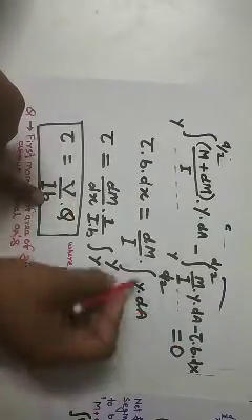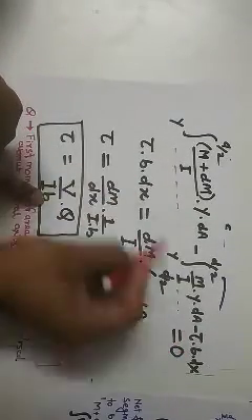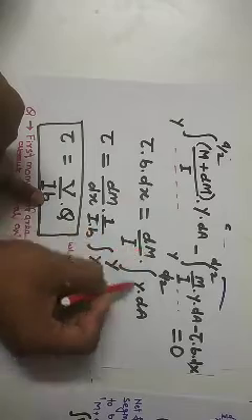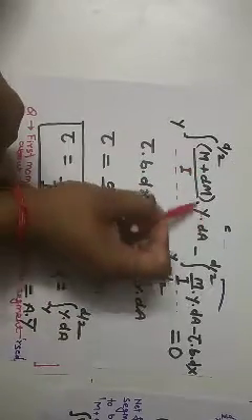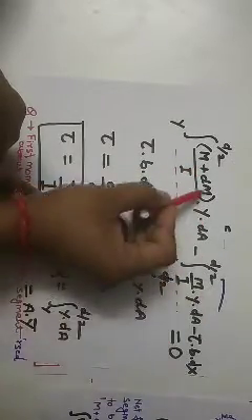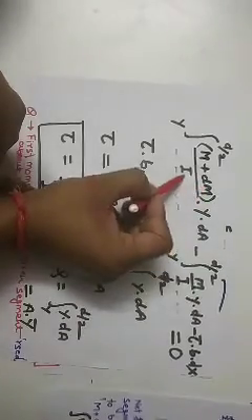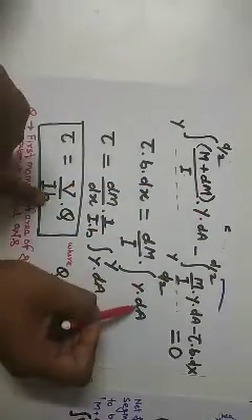Clear? Now tau into b dx equals dM upon I, because M upon I into y into dA and this one will be cancelled out. What is left? dM upon I, integration of y into dA.